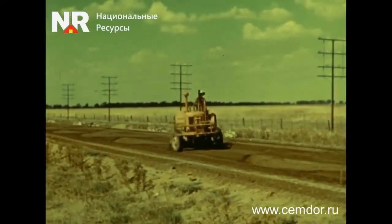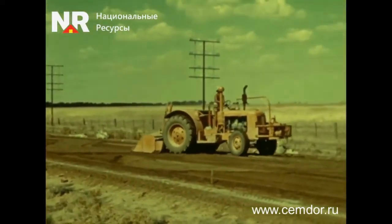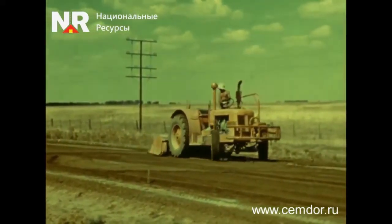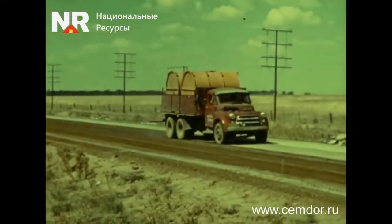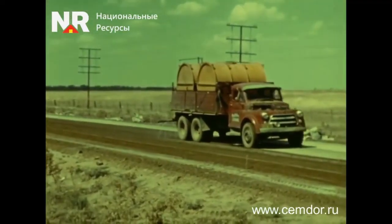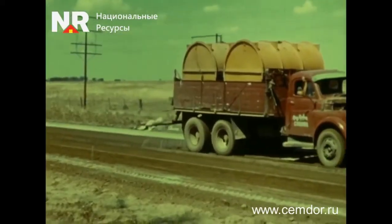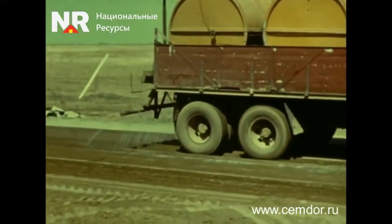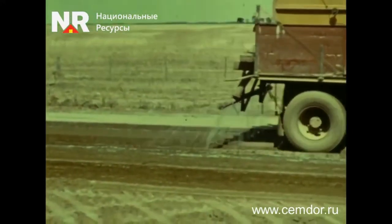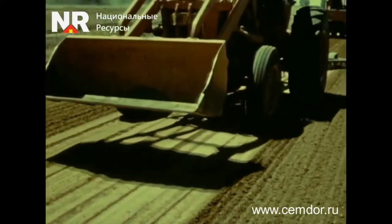Cross-mixing is necessary to eliminate unmixed areas and achieve complete uniformity of the constructed layer. During this operation, the moisture content of the mixture is maintained by distributing water from the tank. In this case, to prevent the formation of irregularities on the compacted surface, cultivation is carried out before the rollers pass.